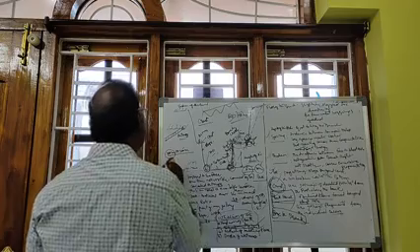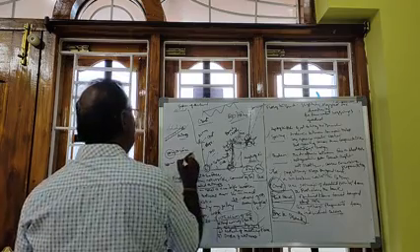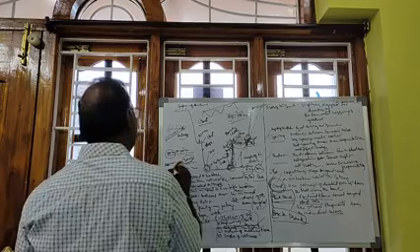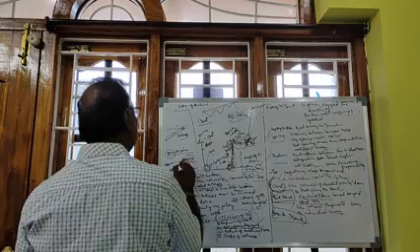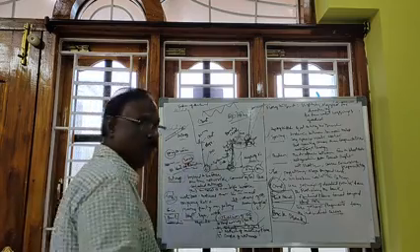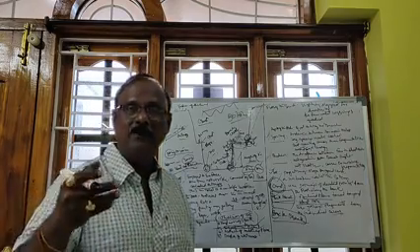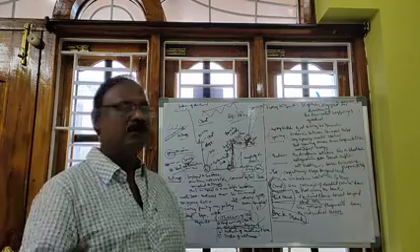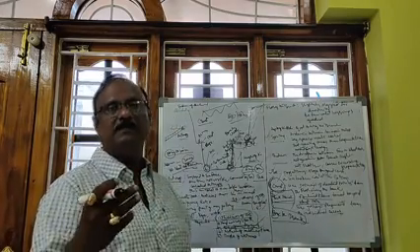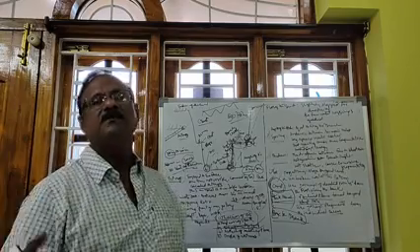But if you put 30 meters for the height of the bench, then only 10 vertical benches are needed, and that is much easier to mine out than 60 vertical benches of 5 meters.